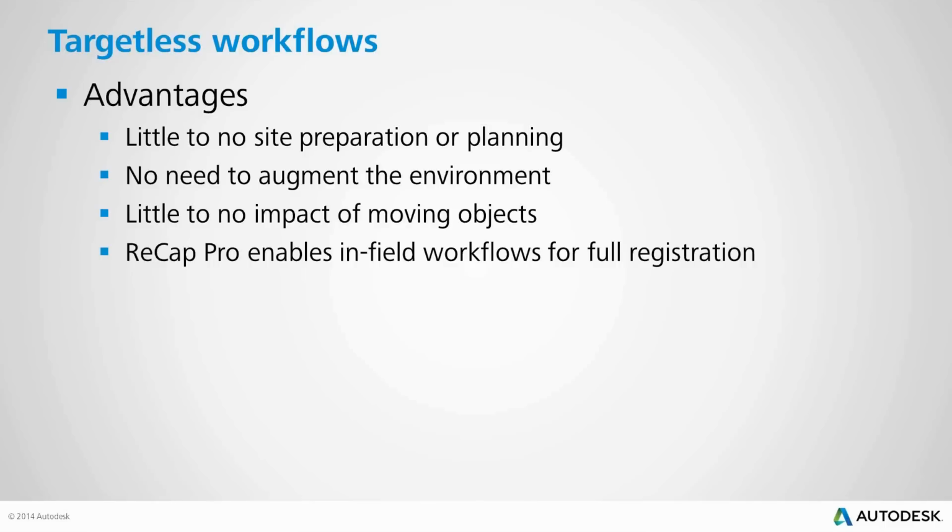ReCap Pro does enable some in-field workflows for being able to do the full registration right in the field. This is great because you can have a fully registered model by the time you leave the site, so you have the confidence that you've got good data, confidence that you've got everything registered, and you've got everything covered that you needed to cover. If for some reason you do need to revisit the site, it's very easy to add additional scans into the data set. No need to worry about targets that might have been missed or something like in the target-based workflow. So a lot of advantages to this. These are a lot of the reasons why we advocate the targetless workflow.